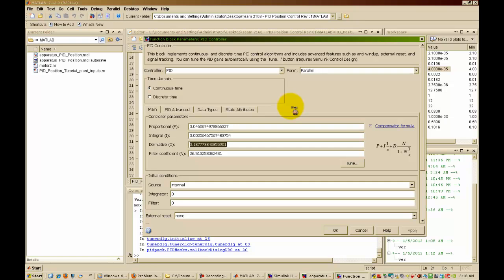So if you run into a situation where you tuned your gains and everything worked well when you did a bench test, but then when you put it on the robot and ran it for the first time, it looked really slow and it wasn't efficient, that's because maybe your controller is too conservative. Try making it a little bit more aggressive, and that should probably help it.